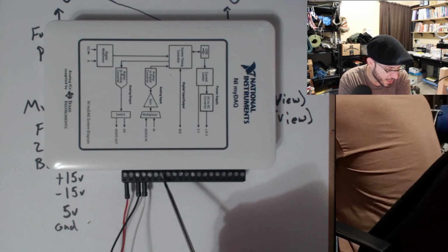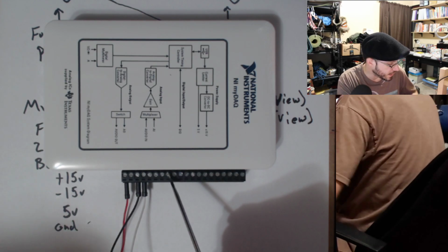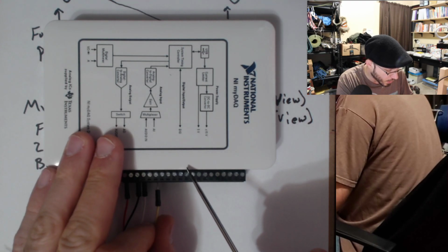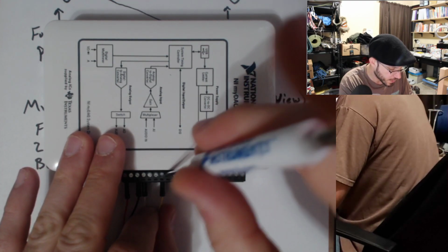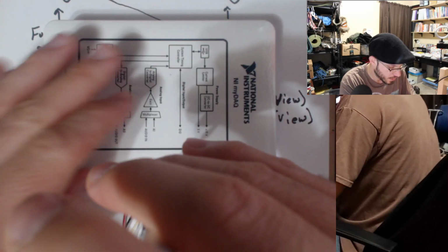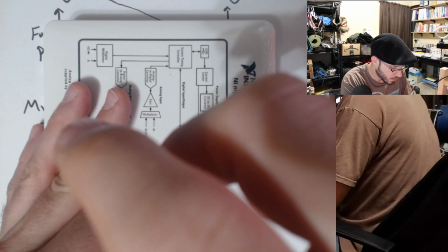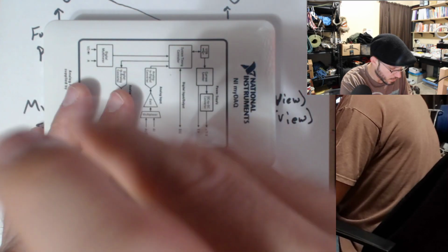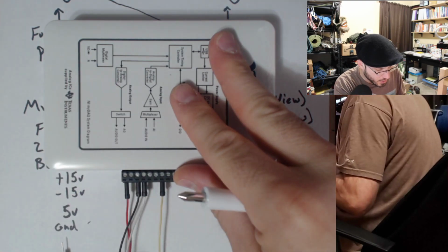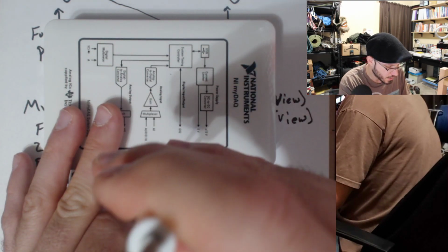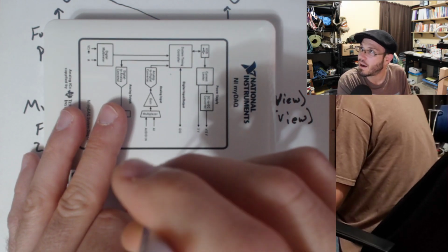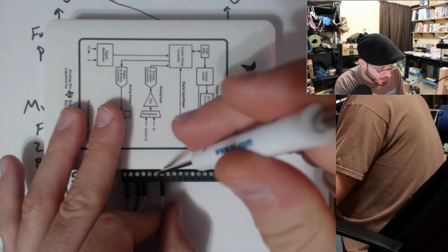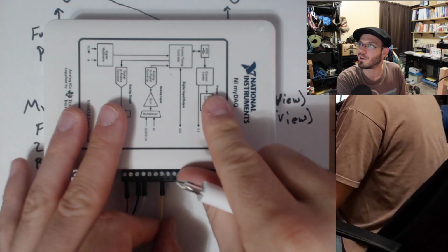And we have a 0 plus and a 0 minus. So for the 0 plus, I'm going to go into a yellow wire for now. This is on 0 plus of A in. And just make sure that those are secure once you tighten that down. You don't need to tighten it very much. You don't want to break these connectors. So just give them a little snug, not too much. Don't crank down on those.